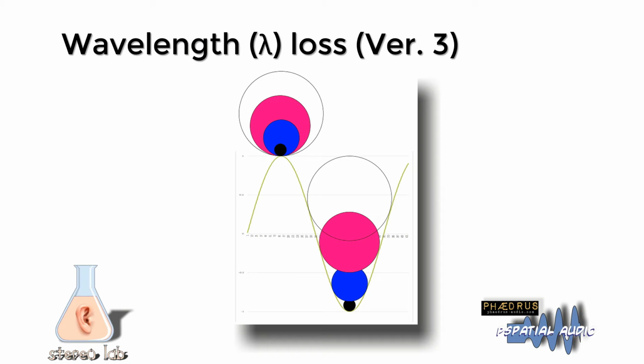Wavelength loss is due to the physical fact that a sharp chisel is used to record the disc, and a rounded stylus is used to reproduce it. And the sharp chisel is capable of cutting sharper corners than the stylus can read, and this results in high frequency loss when the recorded wavelengths approach the dimension of the stylus. And the stylus acts in effect as a physical low-pass filter, as you can see in the picture. And the wavelength on a record is a function of both recorded frequency and groove radius, so scanning loss becomes more of a problem towards the centre of a record.